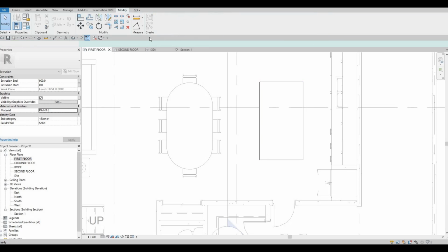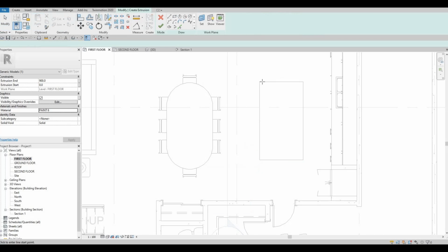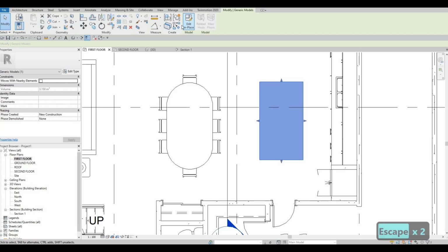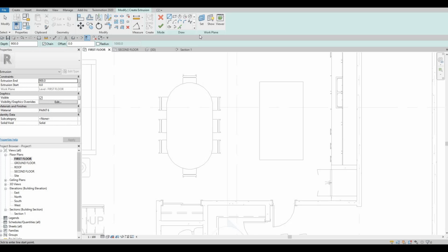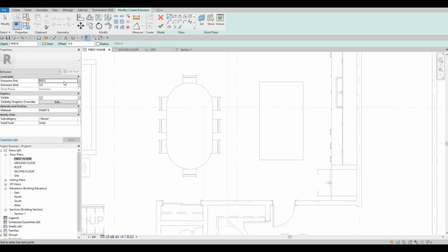Now we could click on finish, and then don't click on finish again, because we're going to create a top from there. So another extrusion. Click on finish first. So delete this, finish here, select this again, edit it in place, and then create another extrusion. We're going to set, pick a plane, and then select the top here so that we could just put 25.